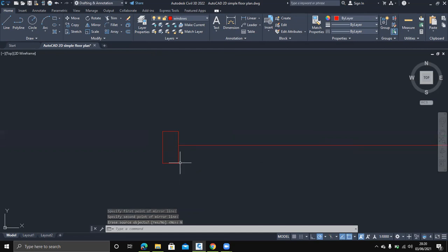So I'll also create an extension again, using the command of drawing a line. I will create an extension of some 40 units again. And then I will draw that line as 1,400 units, and then I will escape, so that I can achieve something like that.